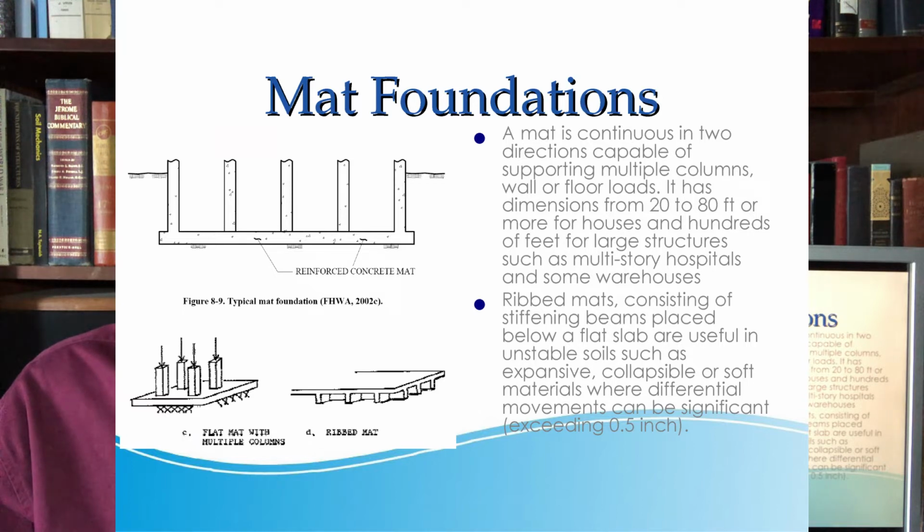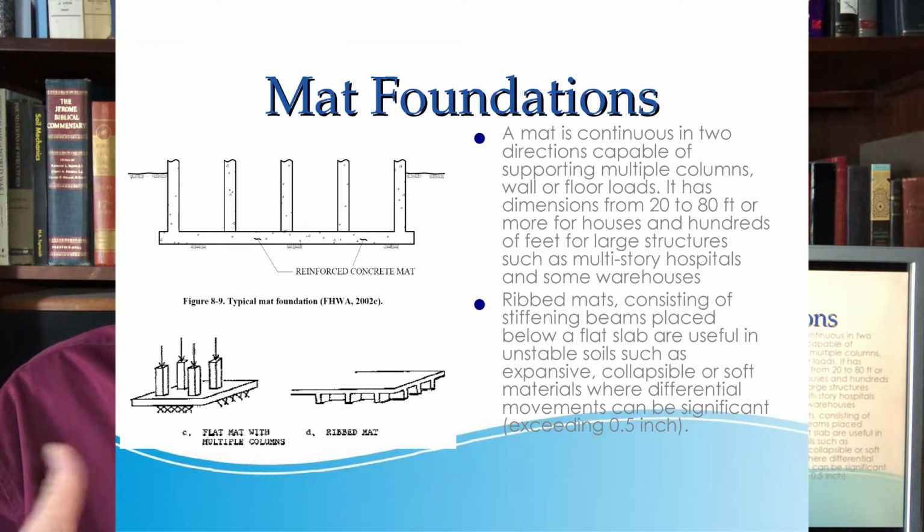Mat foundations are kind of a very special case. It's where the interaction of the flexibility of the foundation and the flexibility of the soil is more important with a mat foundation than it is with a spread footing.